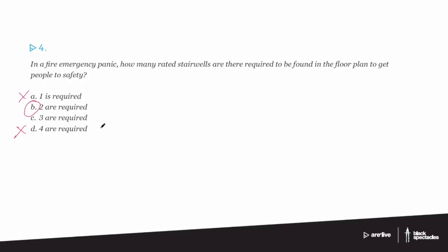The trickiest part, and I'm glossing over it a little bit in this context, since we have an example coming up, is that often you have a very straightforward answer and your immediate inclination is to say, that's the answer. But you do have to keep looking at the next bunch of information, the exceptions to that rule. Often it'll say you need 2 stairs in this situation. But it turns out if you're sprinklered and only 2 stories, you can get away with 1 stair if the distances are less. Suddenly you can get away with 1 whole less stair, which is a big cost saving.